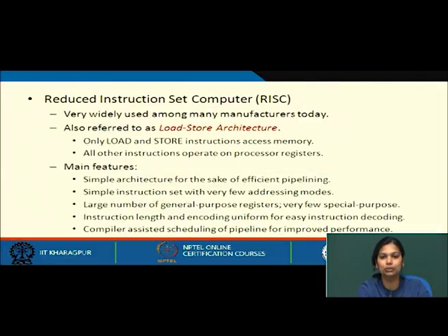Now, coming to reduced instruction set computer. This is the architecture which is used in most of the computers today. Not only computers, but other processors, for microcontrollers and other things, this RISC architecture is followed, very widely used among many manufacturers today. This is also referred to as load store architecture. By load store architecture, we already discussed that only load and store instructions can be used to access the memory, and all other instructions will operate on registers. So, only when memory is required, you have to load it from the memory.